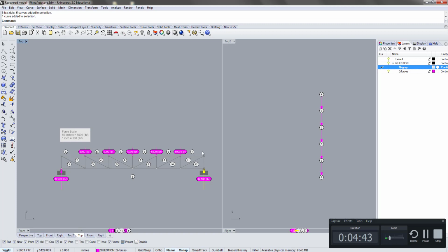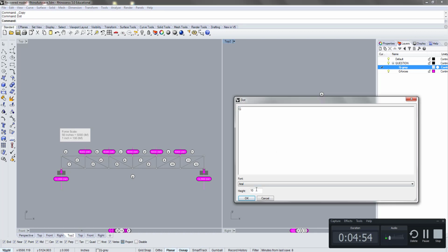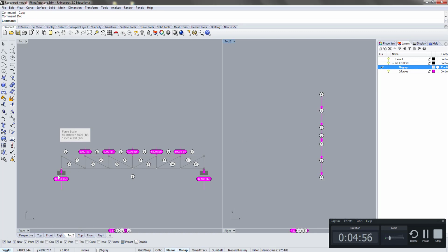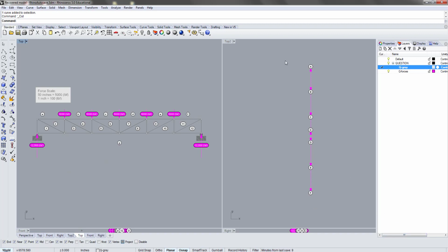This is between F and G, so I would put this on here, and that would end at point G. The next reaction is going to go from G to A, starting from G and ending at A. So now that we've mapped all of the vertical forces, we're done with the outside of the truss, so now we want to focus on each of these points and complete the force diagram, right?